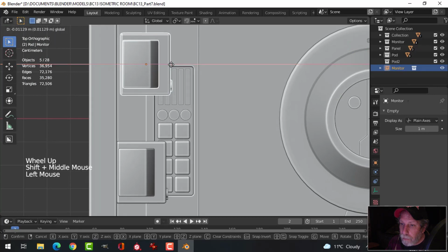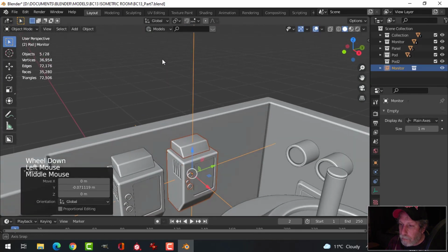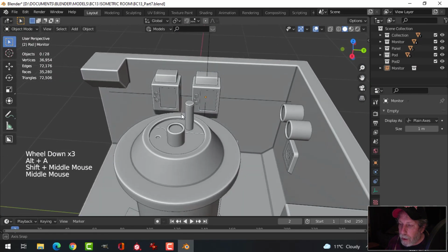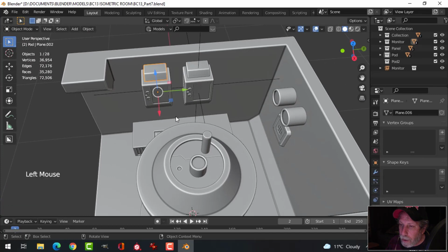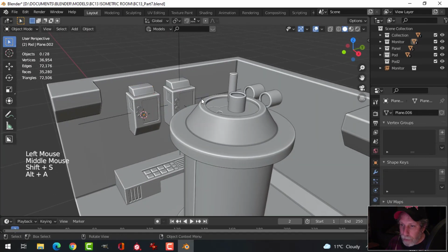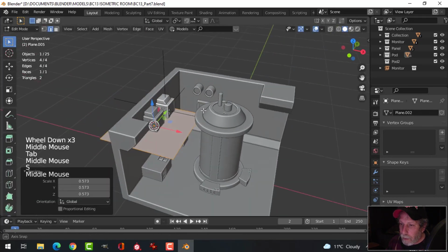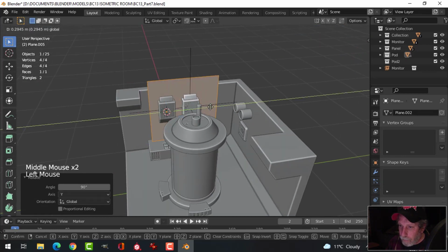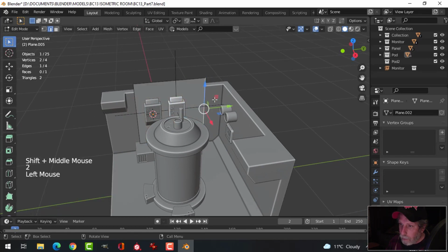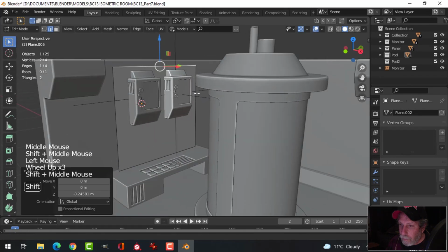Just before I do that, I'm going to move that in a little bit, so sort of similar to this one, and I'm going to move it over. Okay. All right, so let's do this. Let's just select that and bring the 3D cursor there, and bring in a plane in that area. Let's rotate Y 90 and position it up. Select the edges.